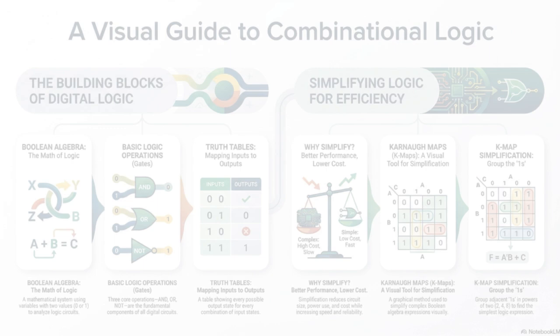Why is that so important in the industry? Why stick to just one gate type? It's a huge optimization choice for manufacturing. Using a single type of integrated circuit, or IC, simplifies the whole production line. It reduces inventory and it standardizes testing. It's about efficiency of scale, not just the raw gate count on one chip.